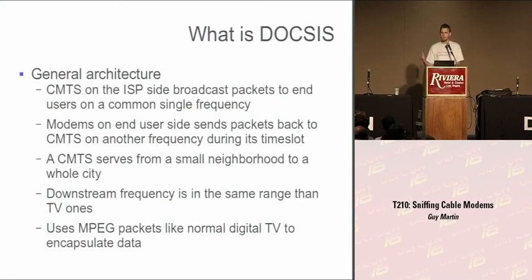Compared to the old 10 megs Ethernet coax cable, the return path is different, meaning it's running on different frequencies. And the modems have time slots allocated to each of them, so they know when they have to send packets. Because of this, we can only sniff the downstream, because the cards that I use are not able to get the lower frequency that the upstream uses. I'll detail that later.